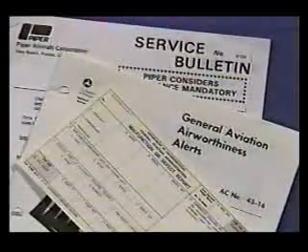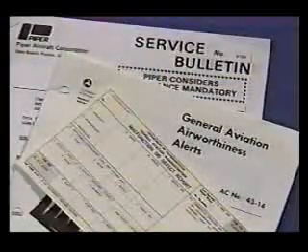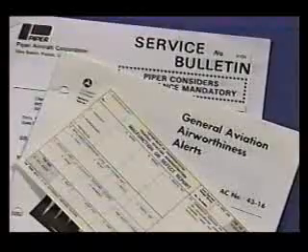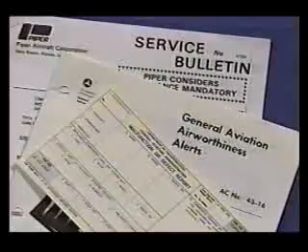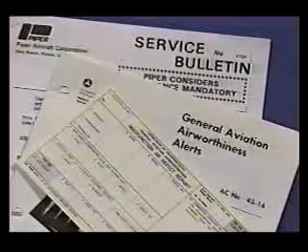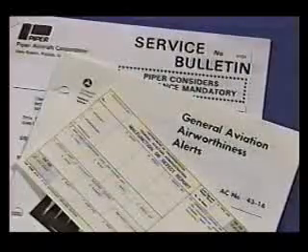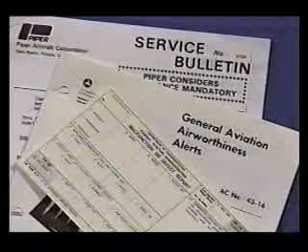Fill out a malfunction or defect report for Part 91 aircraft or a service difficulty report for Part 121 or 135 aircraft. The FAA uses this information to publish AC 43-16, Aviation Alerts. You should also report design deficiencies, which could include anything from an uncoated part that corrodes readily to a design which allows water to collect, creating a corrosion hazard.